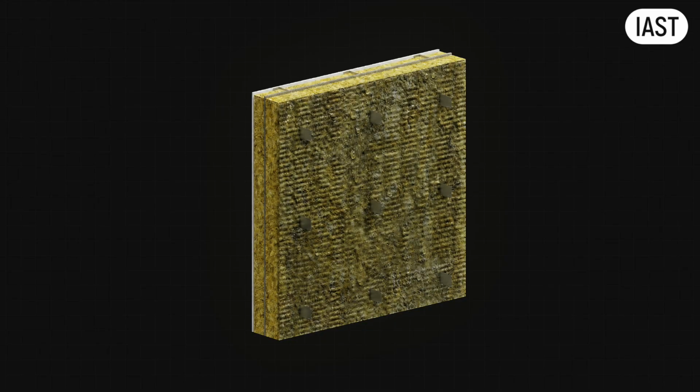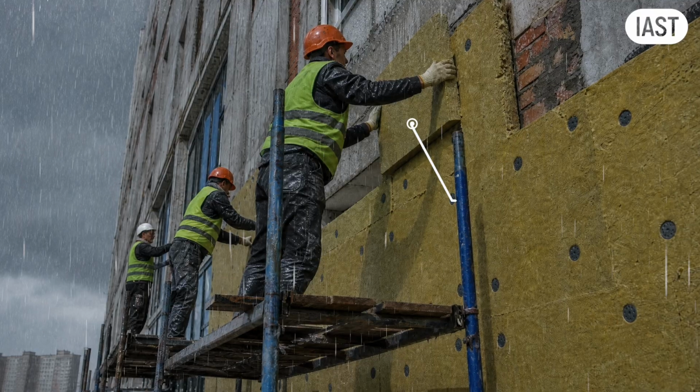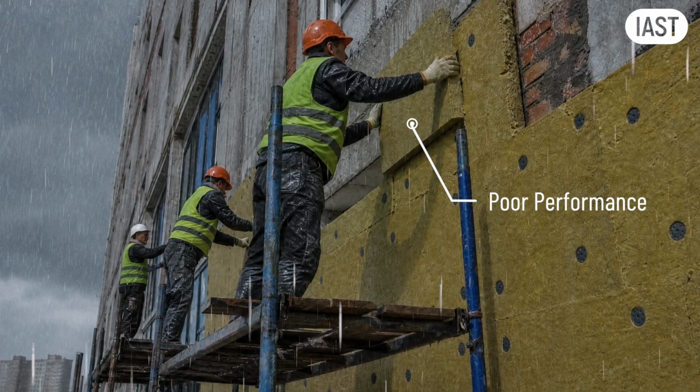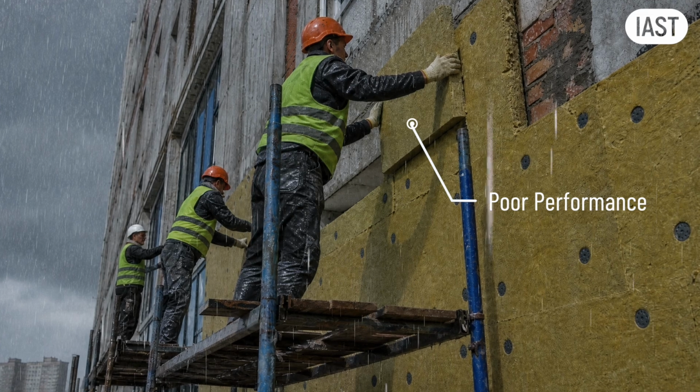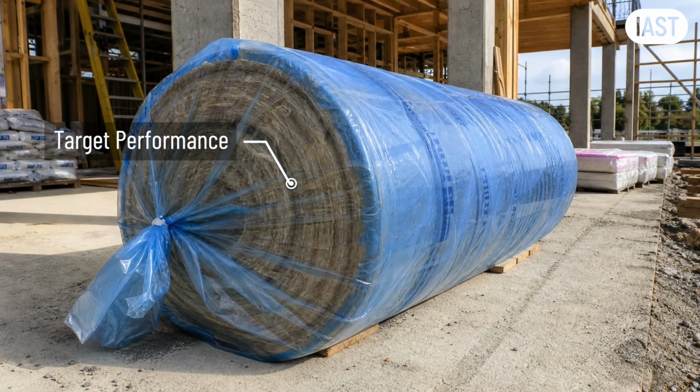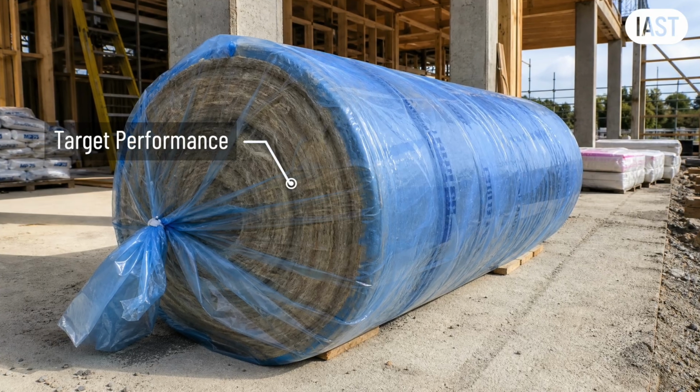Second, moisture. Wet insulation conducts heat more readily than its declared dry value. If wet materials are sealed into the walls before they dry out, that performance loss is permanent. The thermal conductivity rises above the declared figure and stays there. Protecting materials on site is not a formality, it is part of delivering the R value you calculated.